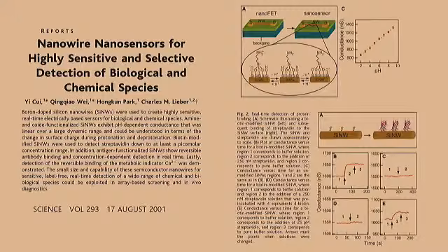The other thing is that the other scattering mechanisms or other things more or less remain the same, and therefore we normally do not expect it. But in these length scales, whenever we have nanowires of these dimensions, what essentially happens is that the surface is basically the dominant thing in these nanowires, and it is possible to modulate. What Abhishek also showed is that there is a significant reduction in the density of states at the Fermi level, and therefore it doesn't have as many electrons as in a bulk metal, right?